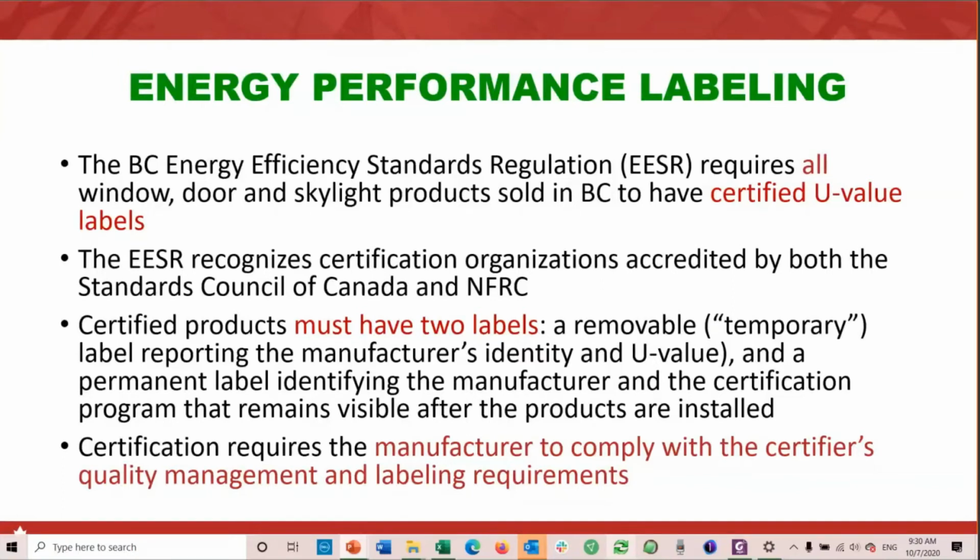On fixed products that can't open, sometimes the label is hidden underneath a glazing bead, just because homeowners don't want to see these product labels visible on their products. Sometimes the permanent marking is actually etched into the glass. So there are different acceptable ways of indicating the permanent marking. It depends on the certification program's rules and which option a manufacturer has selected for that purpose.